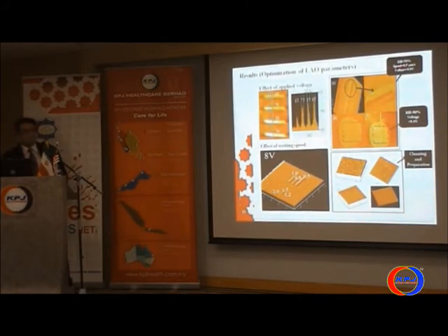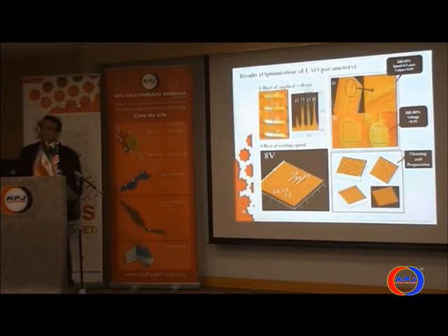Or the humidity. Relative humidity is really important, since, as I mentioned before, the water meniscus and water drops in the air are really crucial for making this oxidation. Also, because we are dealing with the nanoscale, the cleaning process is really crucial. I think we are talking about 5 nanometers, so you cannot imagine how clean the wafer must be.